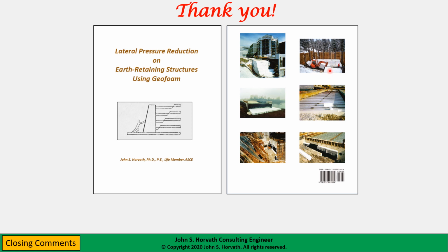This does point out one of the benefits of using geofoams in general for many different applications, is that you could place it in all types of weather. Here you see them placing these blocks in the middle of winter with snow on the ground. And that certainly would have been impossible to do with traditional earthwork or mechanically stabilized earth. Anything requiring manipulation of soil was very easy to take care of with the EPS blocks.